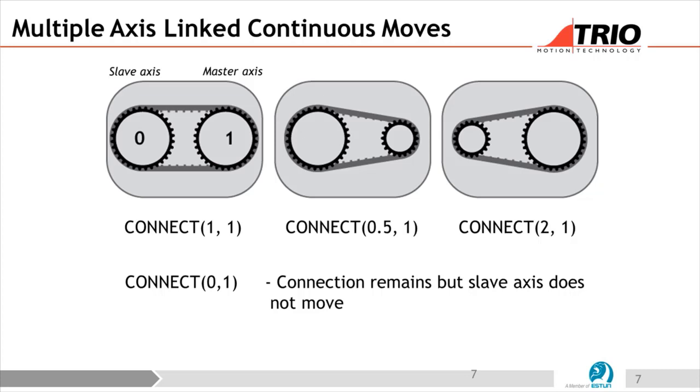So effectively, you need to sync two encoders. Yeah, you're trying to sync completely different scaling. Yes. So if they've got totally different scaling, then you could well see high counts on the high ratios on the connect. But it is a very hard lock. It is like having teeth meshed, only this time they're binary bits. They're encoder edges meshed together, and there's no smoothing or anything like that between the two.